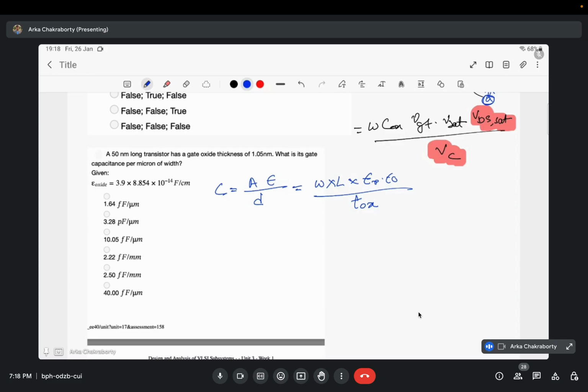Okay, there are interface trap charges, there are other kinds of charges which are introduced during fabrication. The sodium and potassium ions that are present get imbibed in the oxide layer, and they can be lifetime killers for MOSFETs also. If you study the device level physics of it, you will find that most of the charges reside in the oxide or near the oxide. We can approximately take all the charges as present in the oxide.